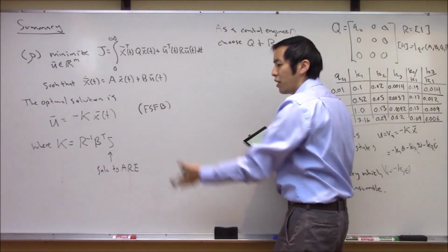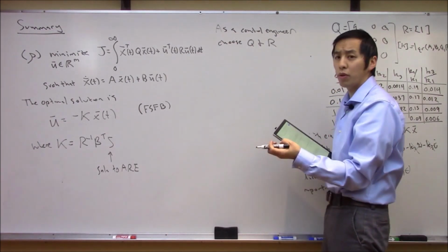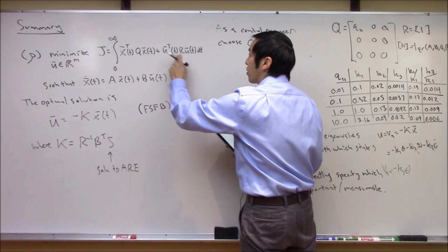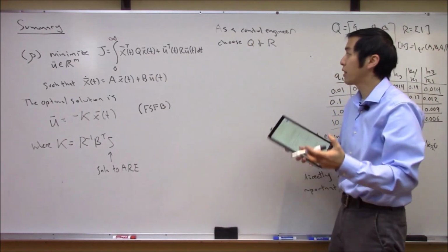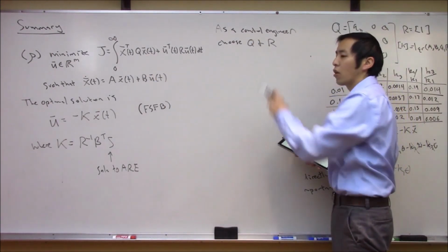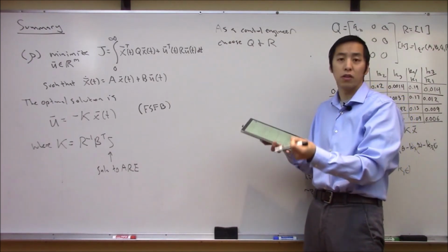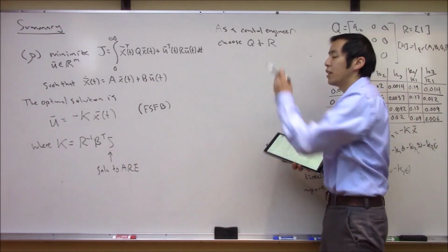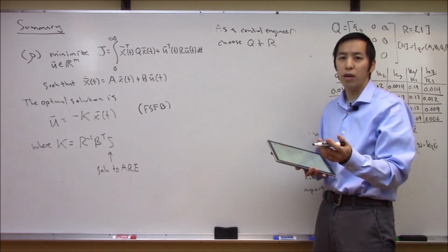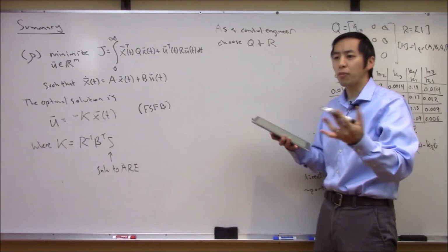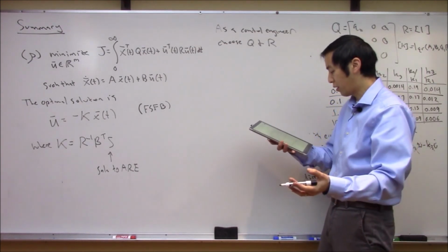And then you run the LQR process here, and it will synthesize a controller for you, which respects this cost function here and tries to find something that is the best here, right? So Q and R are much more helpful knobs to twist because they have direct physical interpretation, right? Q will literally tell you which states you care about in your system, and R is going to tell you which controls are important or cheap or expensive or whatnot here, right?